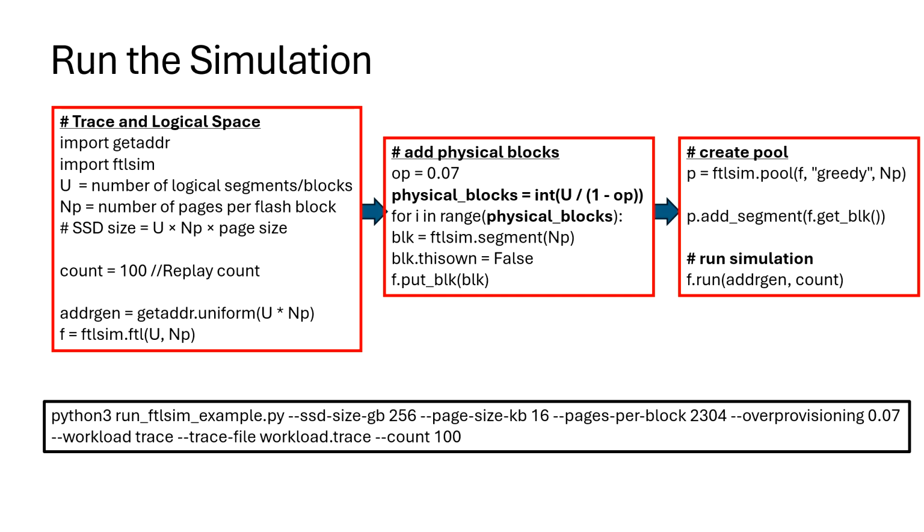An SSD can have multiple NAND chips. Does it assume only one chip based SSD? Yes, this assumes only one raw NAND chip. But if you have multiple raw NAND chips, can you update this too? Yeah, I can. I know where to change. But the basic version is only one chip. Those things are important because you have die level parallelism, and then plane level parallelism will improve the bandwidth. Yeah, plane level is also there.